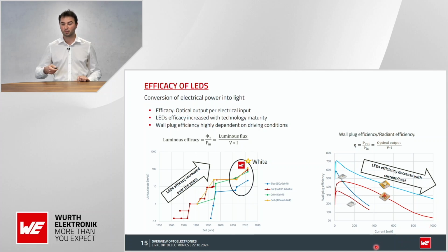So what we learn from this is if you use LEDs in an application, it's always good to make sure to have a good heat dissipation away from the LED, and maybe don't drive them at the overall maximum, because you will lose some efficiency, and if you drive them at the overall maximum, you will also reduce the lifetime of the LED.